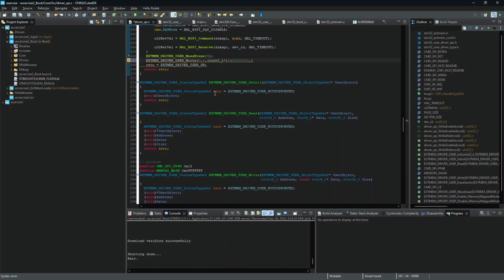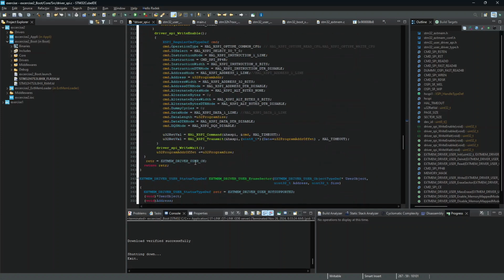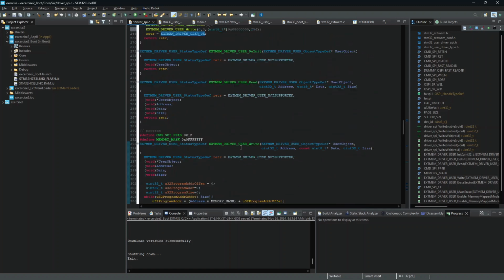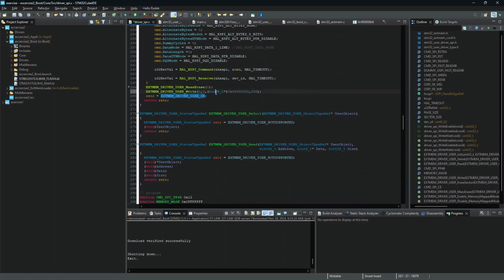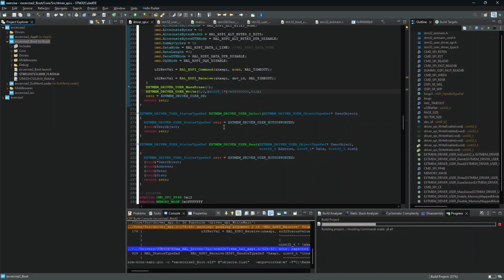This is our flash where this bootloader is located, so we can compare it later on if the values are the same, and we can put 256. And again, I think I filled everything here. Yeah, the return variable, it's okay, and we can check if this will work. I can put 512 to see if I can program even the bigger buffers.